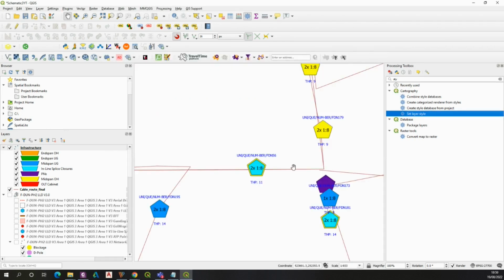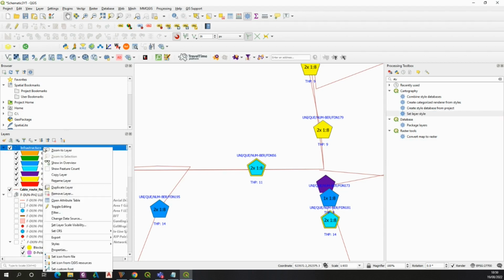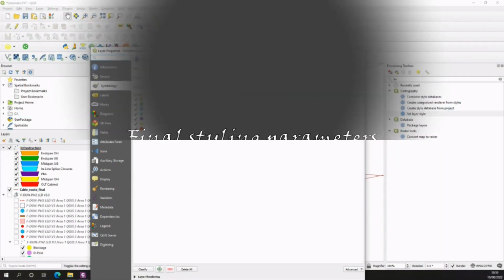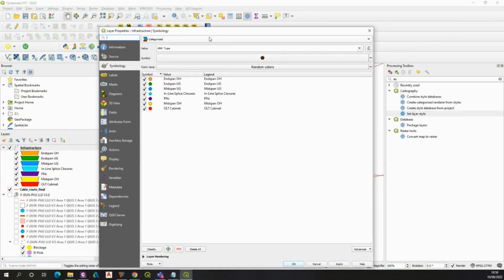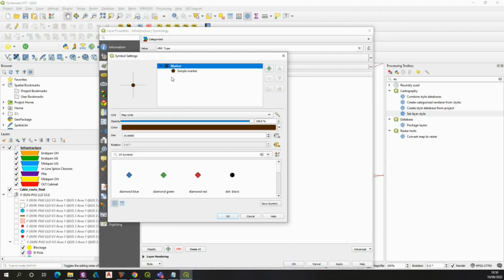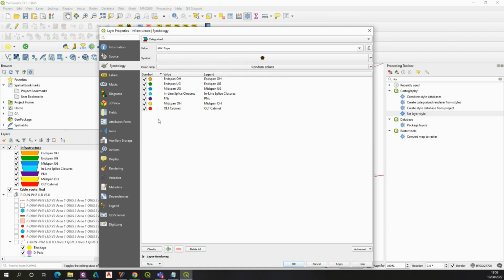Because I haven't run you through the whole styling process, since it would take ages for this video, just for a quick recap I will show you how this style looks, and it will be the inspiration for you for the next time. So symbol again, it's the pentagon, size 15, and unit map units, opacity we keep at 100, which is great. Then coloration is valid for all the particular values which firmly stick to the PDF provided.